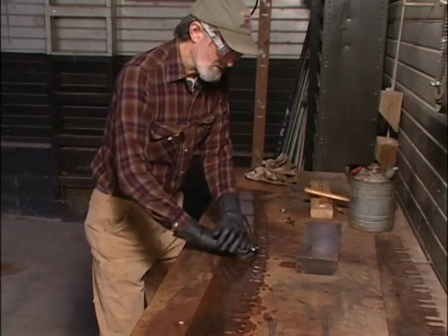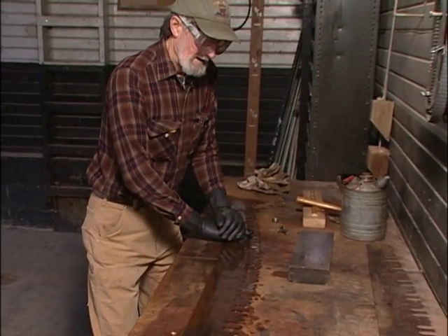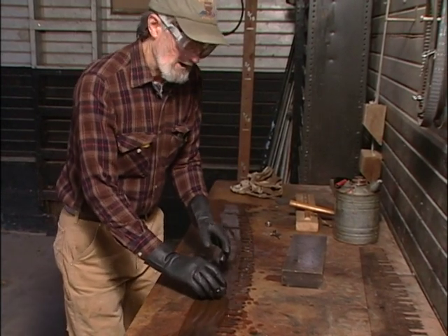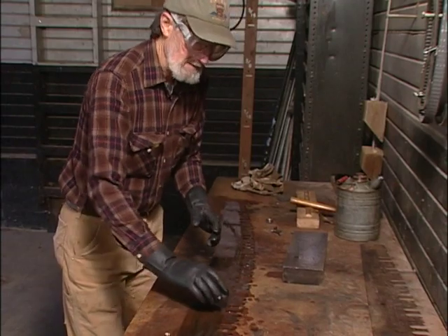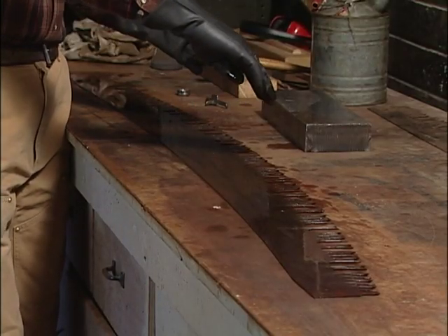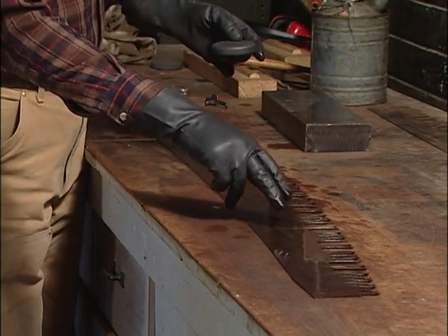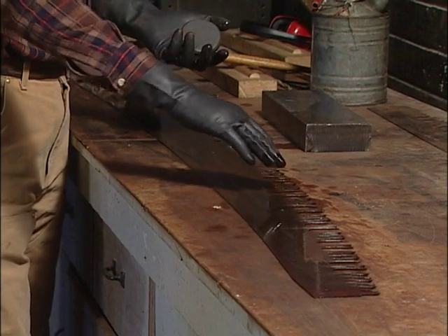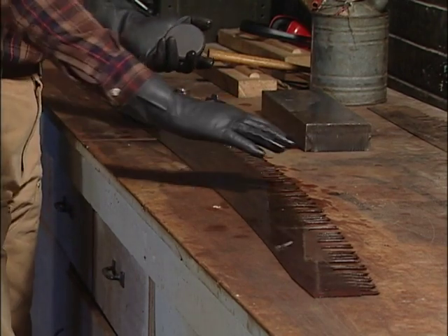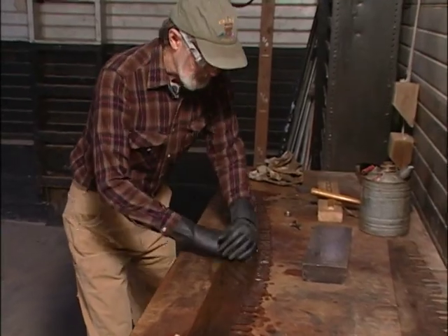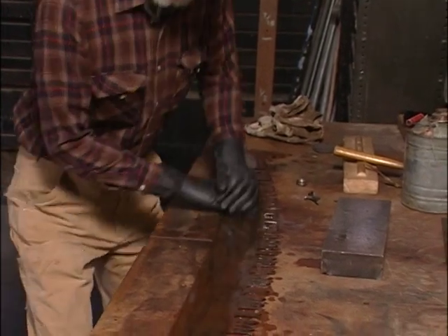Now again, I usually like to run the stone the length of the saw, and even when I'm doing the rakers and the cutter teeth, rather than going up and down the teeth, because going up and down the teeth will leave vertical scratches on the saw. You may be able to see some in here where this has been previously cleaned with a stone whose action has been up and down. You can see the scratch marks in it. Try to use the stone back and forth the length of the saw like this.